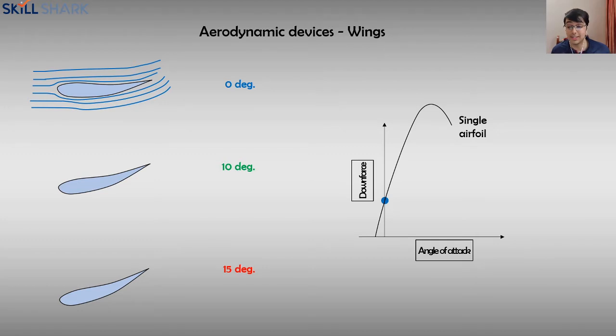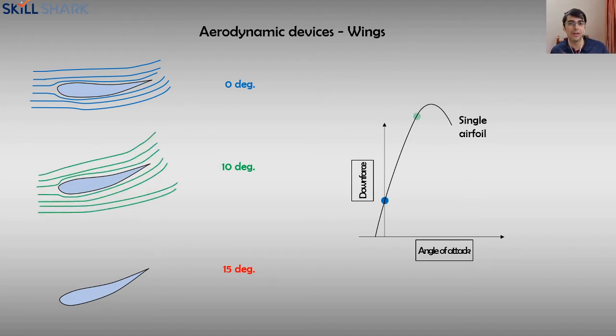Now let's look at 10 degrees. 10 to 11 degrees is where airfoils generally start peaking in their performance. Simplified airfoils, of course, you do have airfoils that can reach much higher angles of attack. But in this case, let's look at 10 degrees. So air reaches this point, it splits, and it goes over, as we see. So this is a lot slower than in this case because it's being hindered by this airfoil. It's having to curve through a much smaller radius, which makes it lose its momentum faster. So there's a lot of high pressure being developed here, and then you have extremely low pressure down here because air is accelerating. It's going a lot more gradually with respect to the air around.